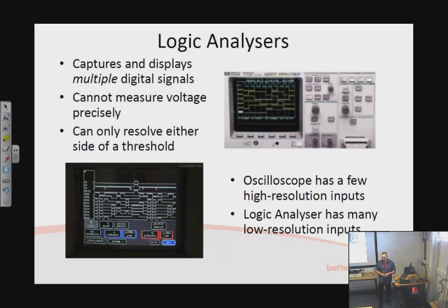And obviously, as long as our digital signal is working correctly, and we can use an oscilloscope to establish that, we can then switch to using a logic analyzer to gather a whole series of information streaming in from our circuit. And so you can imagine that's very useful if we're developing a serial link, or better still a parallel link, or a data and address bus from a microprocessor, a memory interface or something like that.